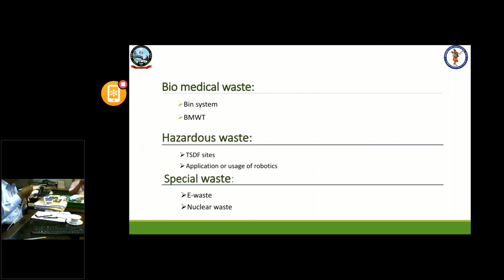You have hazardous waste management and special waste management. In the aspect of biomedical waste, it is an emerging area because the number of hospitals is increasing day by day. You have to collect this waste separately. Do not club it with the solid waste. This biomedical waste can be taken separately in a bin system: red, yellow, white, black, green.